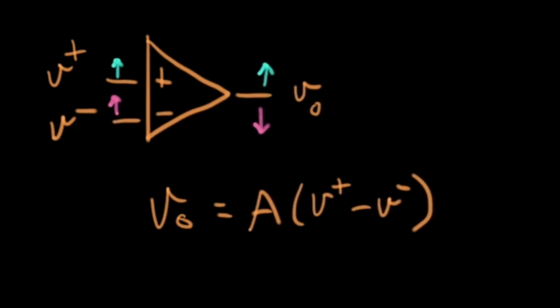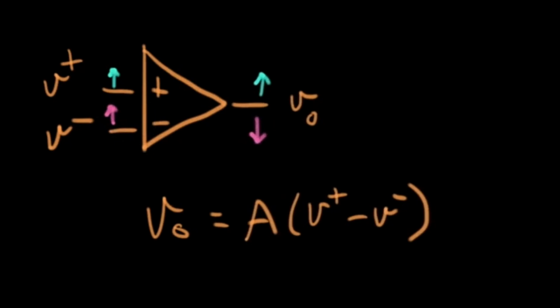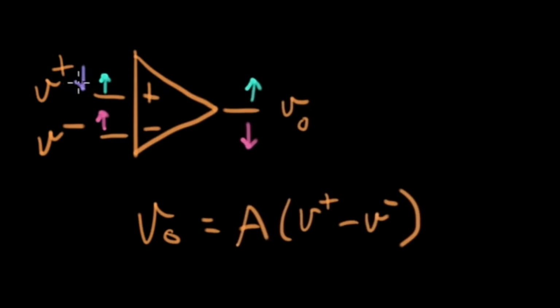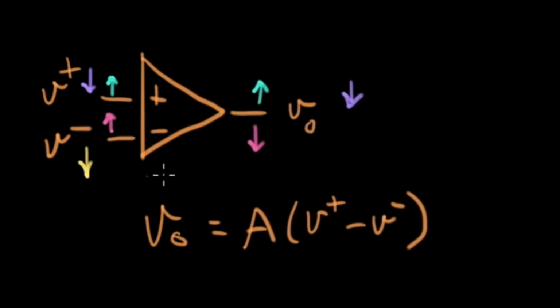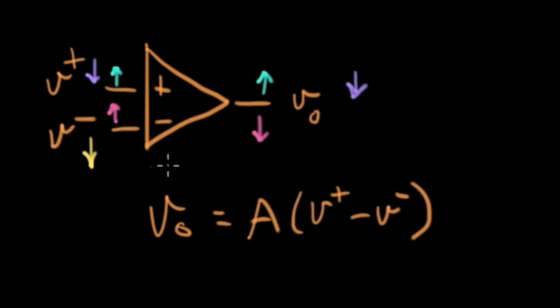That is the way to think about the symbol. When you see it on a schematic page, the positive or non-inverting signal goes in the same direction, and the inverting signal goes in the opposite direction. Here is one final trick I want to share with you, something to be aware of. You are going to see a symbol like this on a page.